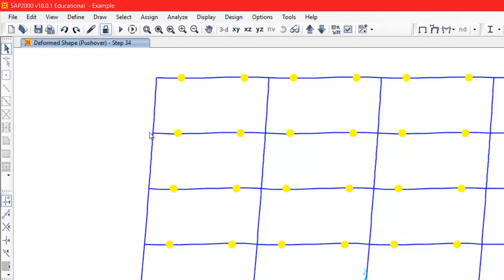You need to report back in this Excel sheet, and you have to be very, very careful when you are reporting those values. You need to report the shear forces. You have the shear force, you multiply by the height, you get the moment. So if you have the total shear force here, it's like 200 kips, you multiply it by h, you get the moment. You do the same here, multiply it by h, you get the moment, and then you report those values back, or you plot them.